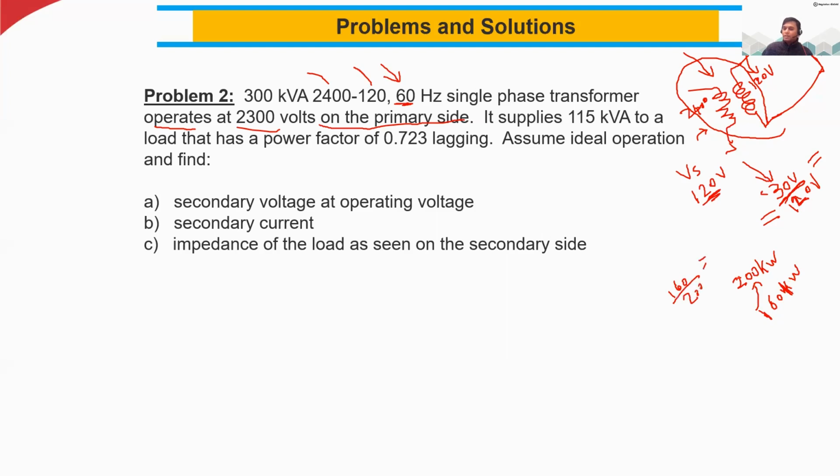If you calculate this, that is the efficiency of this power station. This also depends upon the transformers used in this power station, on how efficiently you are utilizing the transformer. You designed the capacity for 200 kilowatts, but it's only delivering 160 kilowatts. So the utilization factor is somewhere between 0 and 1.